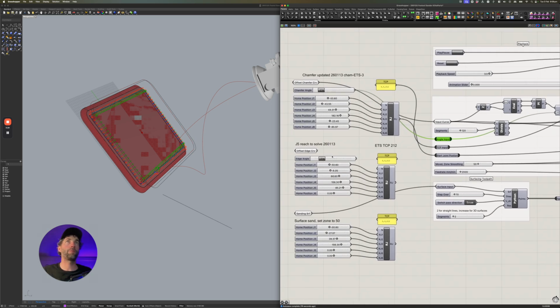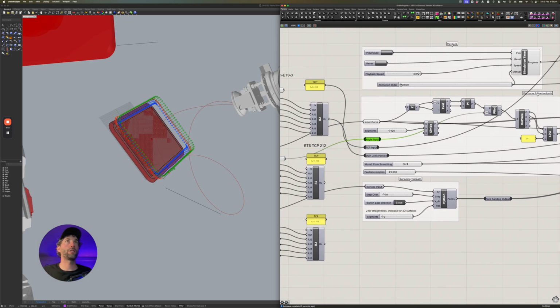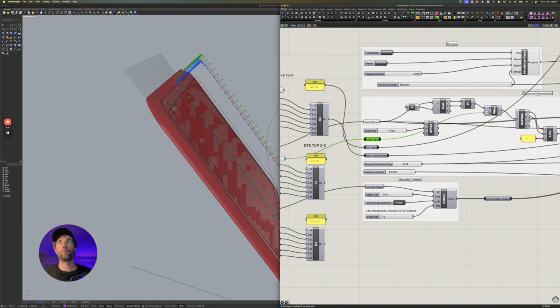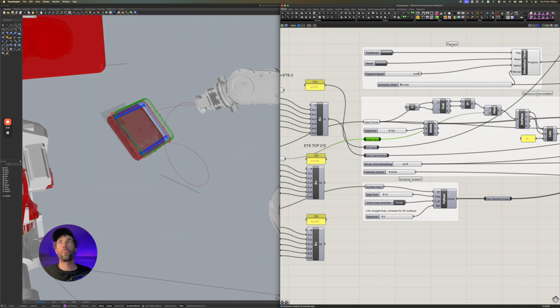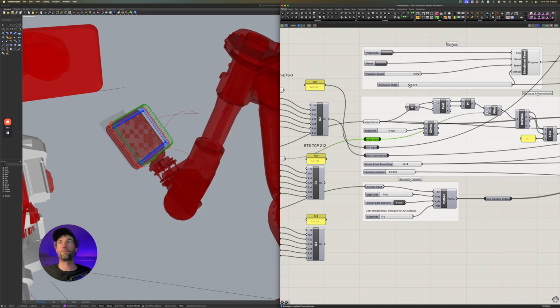I do have a problem here, I've got a reach problem. It's always a reach around problem, isn't there? If I just reset to that. Angle import, TCP can stay, joint position's fine. I've got an issue with this one, trying to capture this little flat 5mm edge of the shelf. This worked with the previous orbital air sander I had set up because it was a shorter TCP.